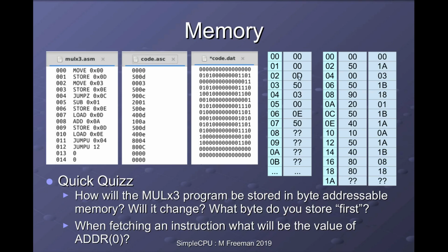We can now view that by placing these memory locations side by side so that we can see the full 16 bits in one row. This will be the low byte and this will be the high byte. So low byte, low byte, high byte, high byte. However, if you look at the store instruction, you can see this has changed. Again, low byte, high byte. So the high byte, obviously containing the opcode, remains the same. But the low byte, the address, has changed.